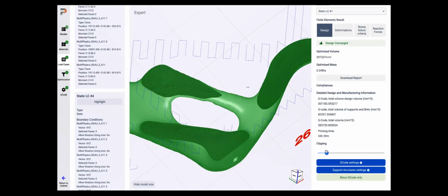So definitely, part orientation on the build plate will have an effect, and Airbus colleagues ran a study optimizing the part for various orientations and found the best orientation. Maybe Inga here on the call can provide a little more information, but definitely orientation matters. And in the future, we plan to include the optimization of the orientation as part of the workflow.